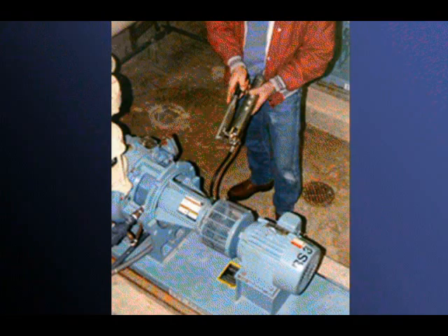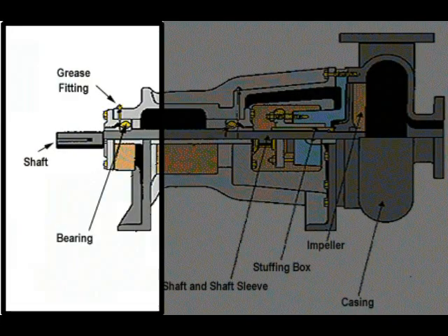Be sure to remove the vent plug before adding fresh grease to the bearing. Not doing so can build up enough pressure to cause failure of the bearing. Also remember to replace the vent plug after greasing. Extra caution is required in units with only one fitting in order not to over-lubricate.